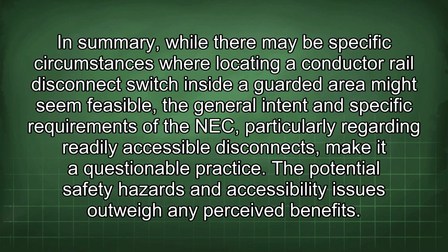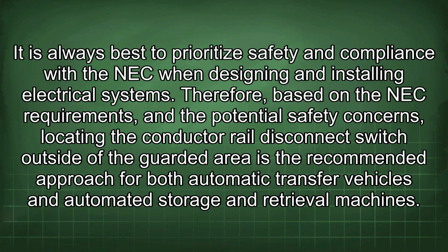In summary, while there may be specific circumstances where locating a conductor rail disconnect switch inside a guarded area might seem feasible, the general intent and specific requirements of the NEC, particularly regarding readily accessible disconnects, make it a questionable practice. The potential safety hazards and accessibility issues outweigh any perceived benefits. It is always best to prioritize safety and compliance with the NEC when designing and installing electrical systems.